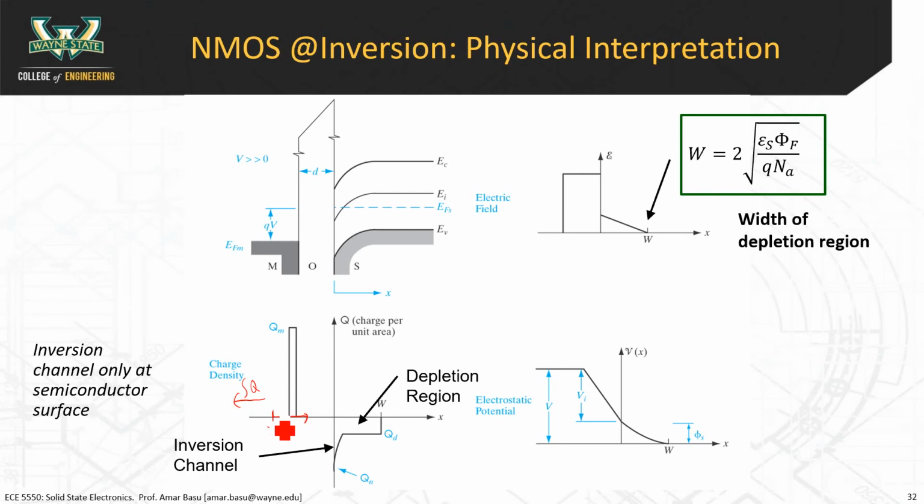As we move through this large area of charge, the electric field is going to increase. So notice that the electric field increased here suddenly. If I drew the electric field on this plot, it would just go up very suddenly here, and then it would be constant like this. So this is the electric field. And that's the same thing that's shown here on this right diagram.